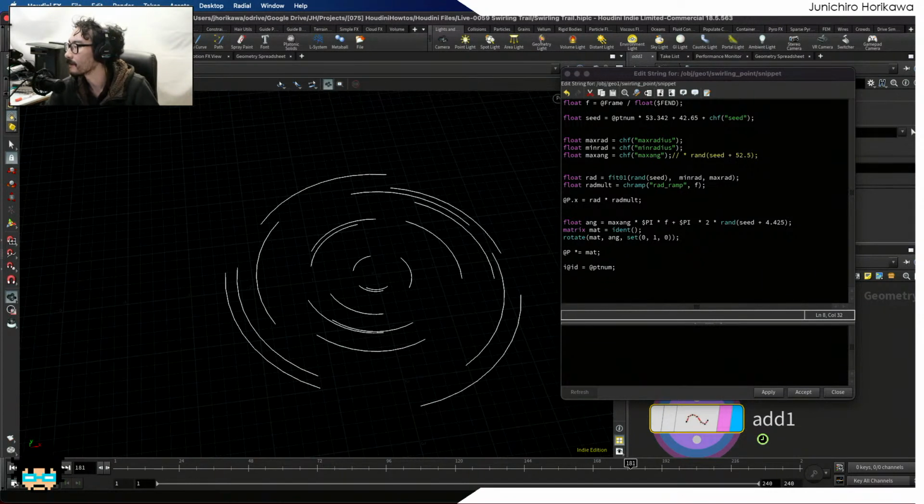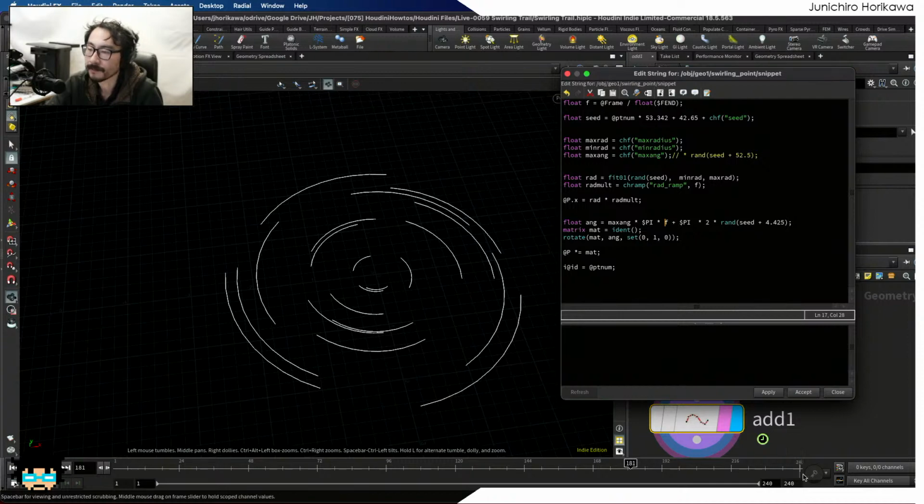And in order to do that, I am going to use a ramp parameter to be able to control that kind of speed. So let's see how I can do that. I am going to modify this f value, which is currently from 0 to 1, from first frame to end frame, which is a linear value. But instead of making it linear, I'm going to make it again a sine wave-like curve. Or cosine-like wave. I could create some differences on the speed based on the frame.